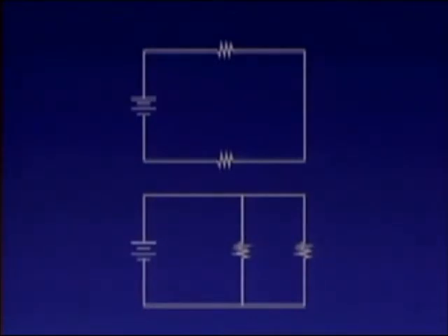If each path is carefully traced, you should notice that each individual path is connected to the negative and positive poles of the power supply. In other words, each separate path has the same voltage source. When resistors are connected in a circuit this way, they are said to be connected in parallel. Each separate path is referred to as a branch. Each additional branch in a parallel circuit has an effect on total current. To see this effect, you'll build a parallel circuit on a breadboard.